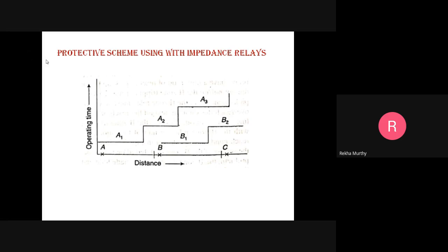It is a very high speed unit and is used for the primary protection of the protected line. This operation will be very instantaneous, around 1 to 2 cycles. This unit is not set to protect the entire line, to avoid undesired tripping due to overreach.